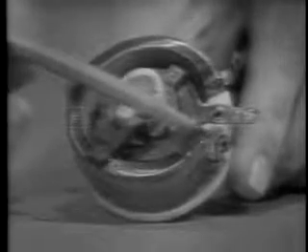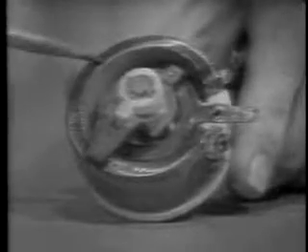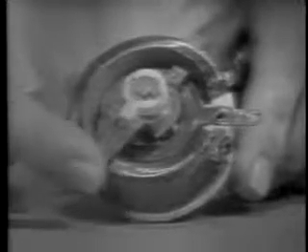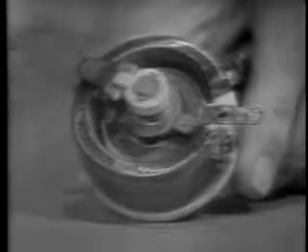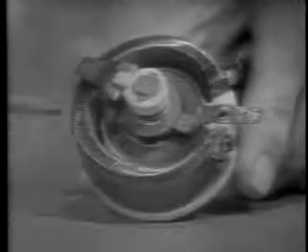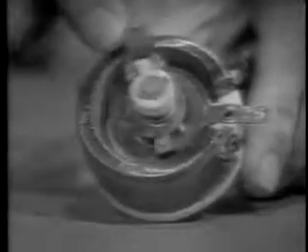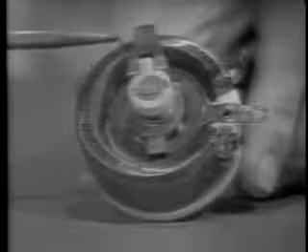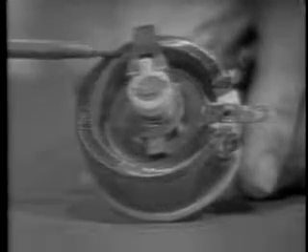Another common type of wire-wound resistor is a variable wire-wound resistor. The wire is here in this semicircle, and it's a fixed resistance from this tap to this tap. The variable part of the resistor is provided by this contact. For example, if I move the contact to here, I've increased the length of the material that I'm using from the contact to this terminal. Therefore, I've changed the resistance. When I move the contact, I change the length of the wire, change resistance. So a variable wire-wound resistor. Again, you can select several different values of resistances from one resistor.